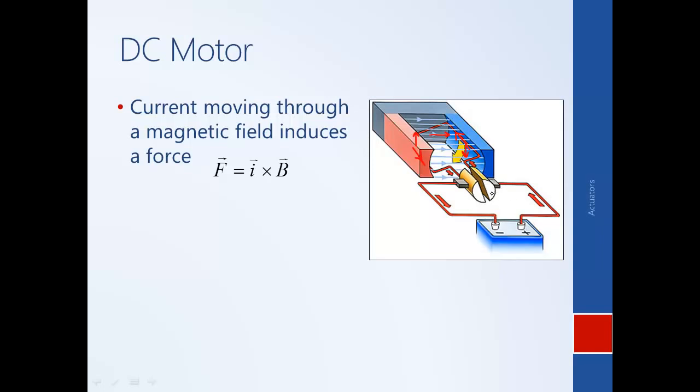So this is sort of broken half rings such that when the motor coil flips, this side is no longer attached to this side of the battery. Rather, it's attached to the negative side of the battery, and that in essence causes the electricity to switch directions, keeping the force and the resulting torque always in the same direction. So it's pushing down. When it flips over, the current switches direction, so it continues to push down. That will keep the motor spinning in the same direction.